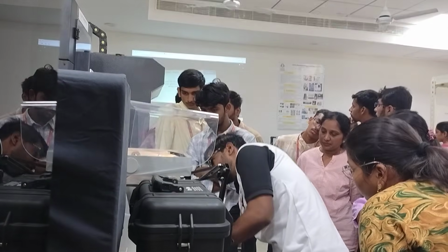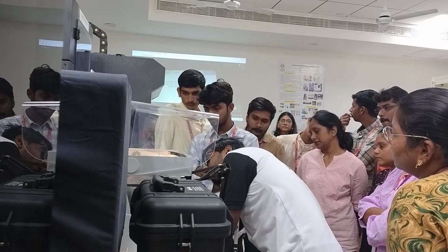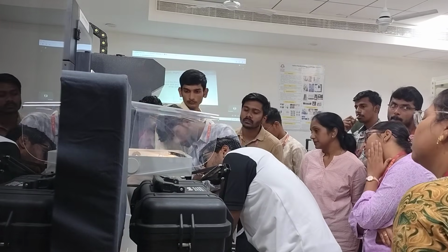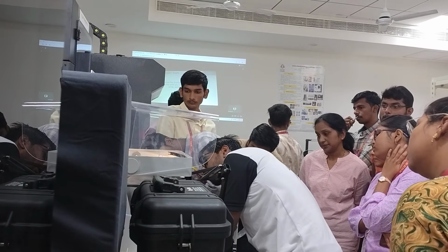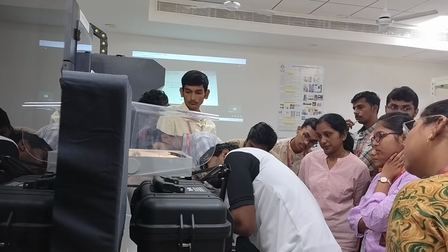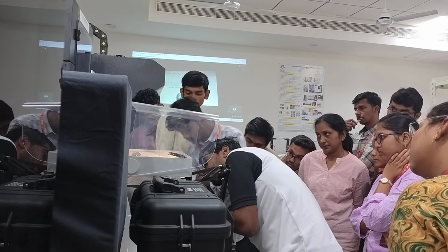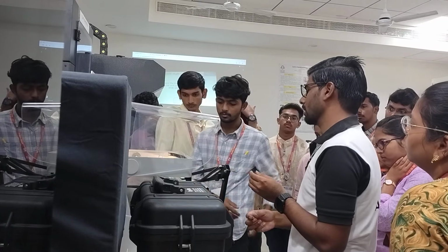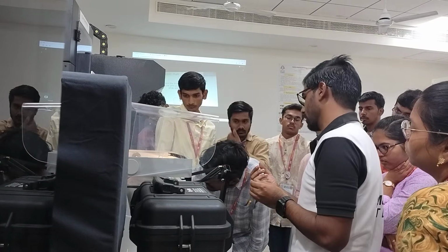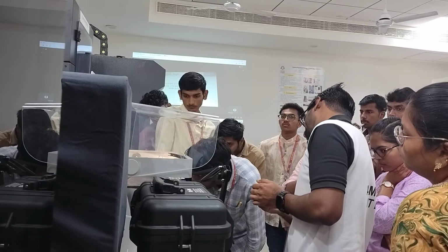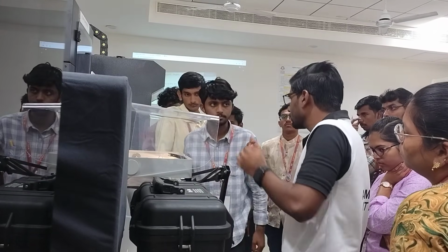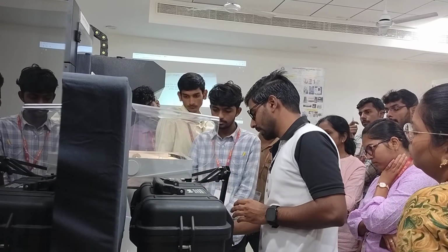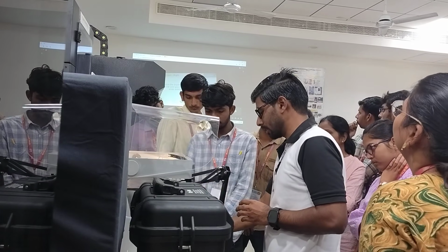Adjust the thumb screw directly. I'll have to adjust it so that there is a small friction. It is not going in so easily, but it is not coming off very easily either. So there must be a small friction compared to the normal area. One of you can just move it and see. There must be a small friction. That is how the shims are supposed to be used. You see, there is a small resistance. When there is a small resistance, we have to just stop. I can click on next.